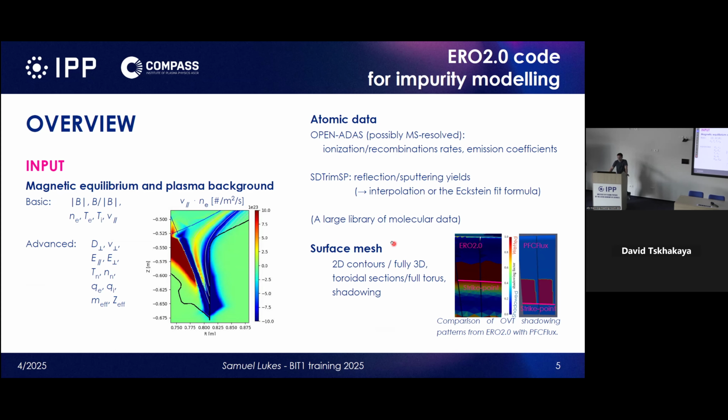Typically, you mentioned you try to resolve at least the plasma sheath to some extent. But then you also need the appropriate meshing to go with it. I assume you're not resolving the sheath everywhere. We always assume that the sheath is taken just in the normal direction from the surface.